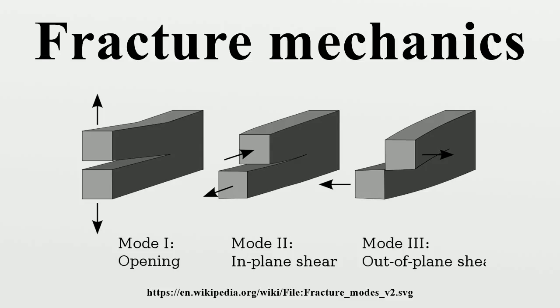The R curve is a plot of the total energy dissipation rate as a function of the crack size and can be used to examine the processes of slow stable crack growth and unstable fracture. However, the R curve was not widely used in applications until the early 1970s. The main reasons appear to be that the R curve depends on the geometry of the specimen and the crack driving force may be difficult to calculate.